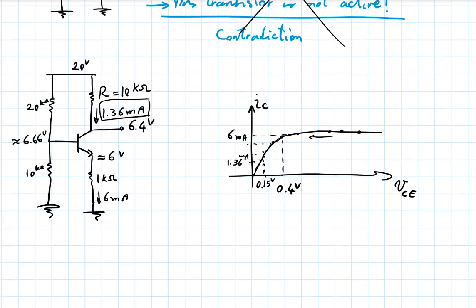What is the base current here? Can we still assume that it's 0? So far we have assumed, but I'm asking whether that assumption should be challenged or not. Yeah, but we said that the base current is beta times less than the collector and emitter current. So if you divide 6 milliamps by 100, you would get 0.06 milliamps. That's pretty negligible compared to the current in those resistors. Is that correct here?